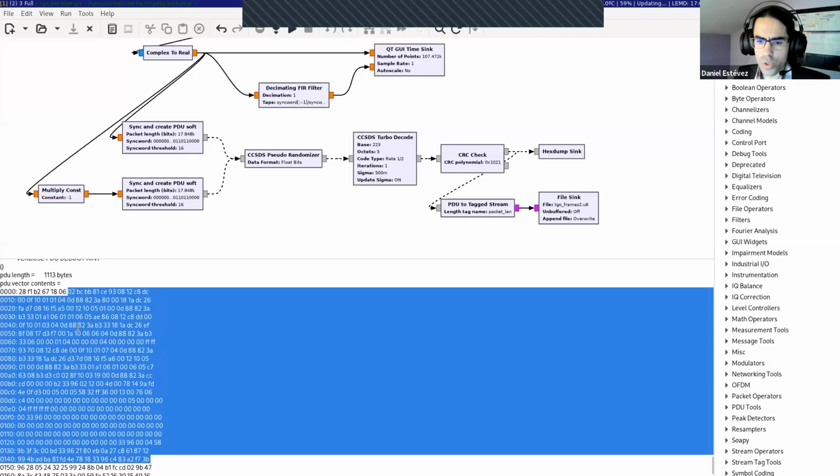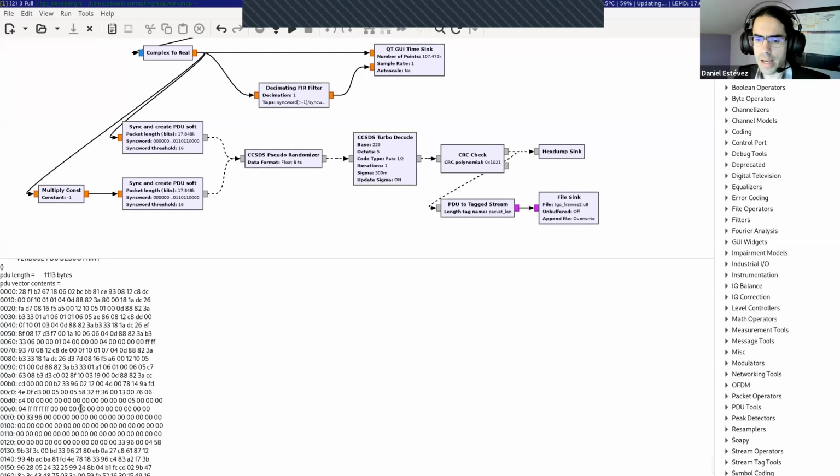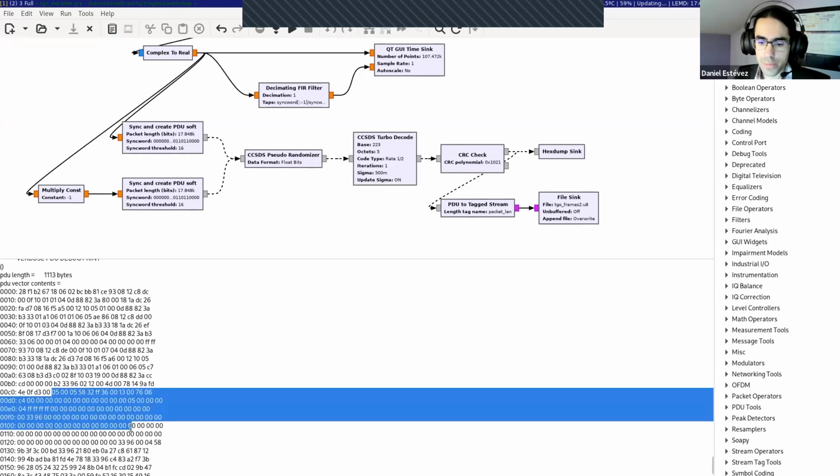Everything else, you can think of it as a continuous stream of information in which you have space packets arranged back to back, as if it was some kind of sausage. And the way to know where the links of this sausage are, or where the space packet boundaries are, is because of something here in the header called first header pointer, which points at the beginning of the first complete space packet within the payload.